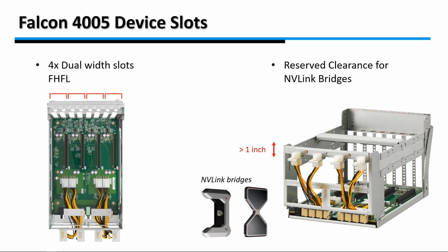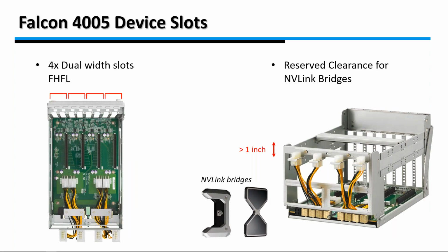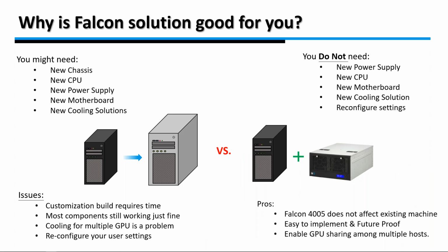For the other RTX 3090s with 3 fans, the dimension is 2.5 slot or 3 slot. The fan-type RTX 3090s take too much space and waste 1 or even 2 more PCI slots. The Falcon 4005 has been designed for the RTX 3090s in power, heat dissipation, and dimensions. Now, in what scenarios is the Falcon series your best choice?